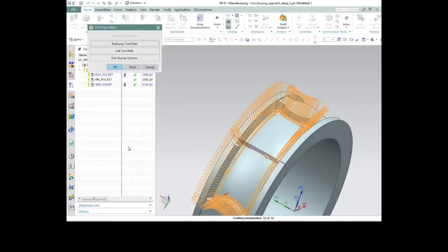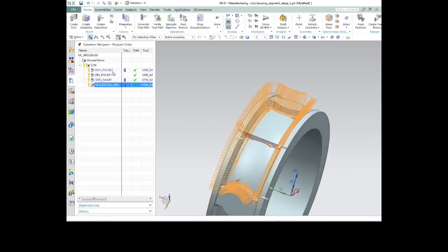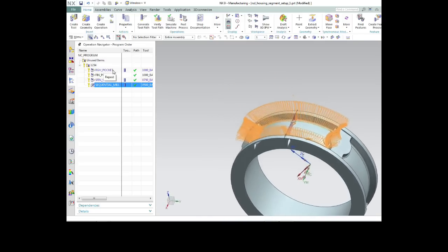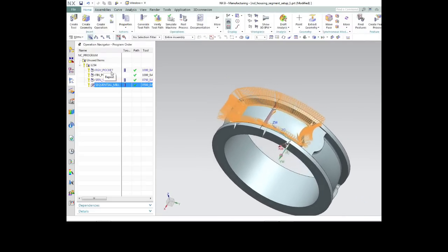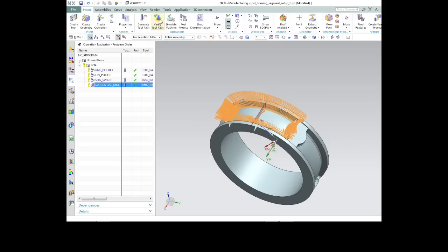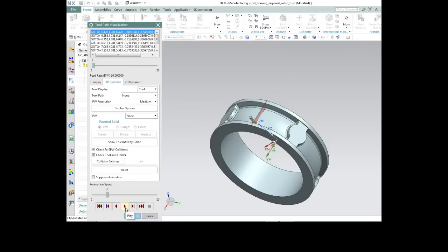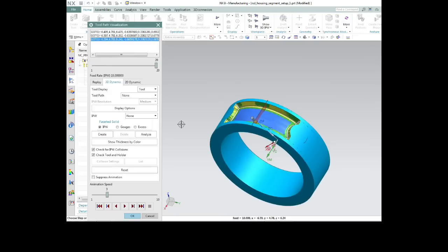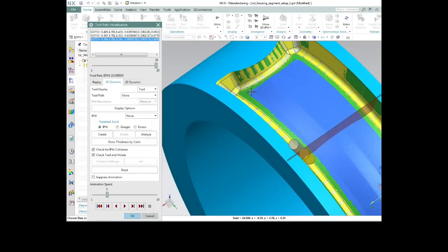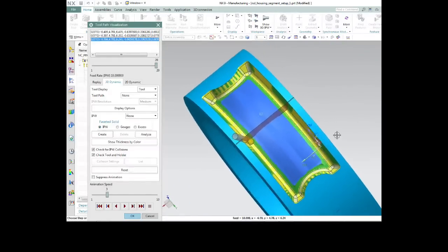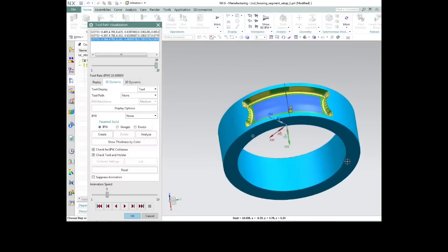So now when you get all the way around, or when you want to end the cut, you just say end operation here. Say OK. Now remember, your avoidance geometry is not done here, but you would want to do that before you get started with this. I just wanted to get this to the point where I could show you the results. And there it is. Of course, there's still a few little nubs in here that you need to clean out, but we just got a 5-axis cutter path all the way around with Sequential Mill.